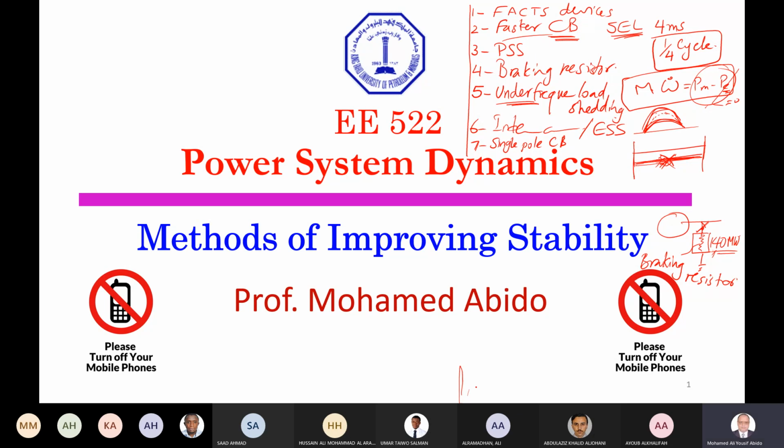And usually when you have a circuit breaker, you trip or isolate the faulted phase or faulted line, and then the circuit breaker will close again after 3 cycles or something like this. Most of the faults are cleared by itself. If the fault is cleared, that's fine, we will go on smoothly. If the fault is not cleared, the circuit breaker will open again, and you may repeat this once again and so on.